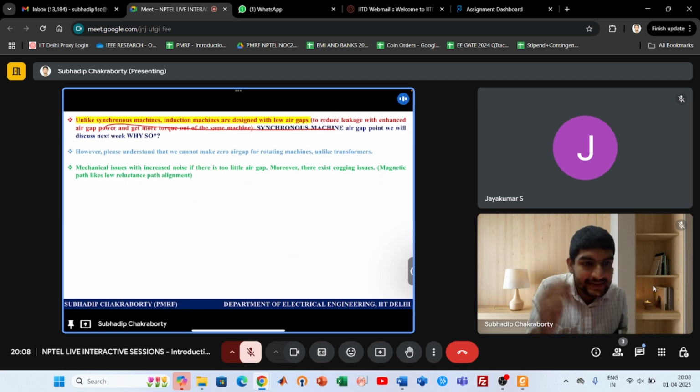Now, if we increase the distance between stator and rotor too much, some flux will come and not link the rotor. That we don't want, because then the coupling field strength reduces. Why? Because if less flux cuts the rotor, less voltage is induced. Less voltage induced means less torque, because the rotor's magnet strength reduces. And if the magnet strength reduces, less torque will be there, because torque depends on the strength of the magnet and the angle between them. Think like that.